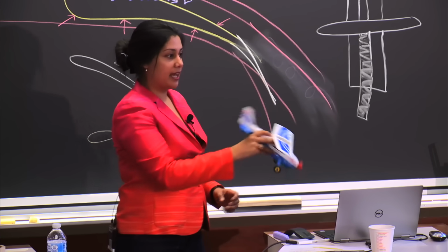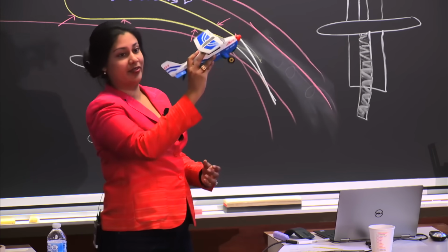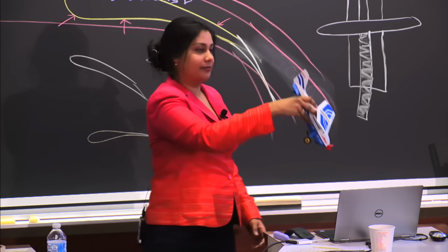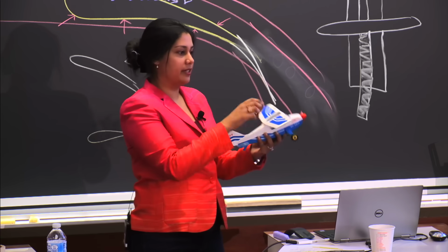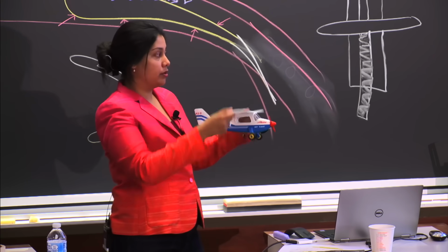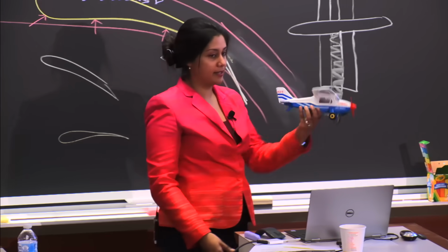So pitch nose down. You might hear that a lot in case you're getting close to stalling because your angle of attack is getting too high. They might say nose down or pitch nose down. You also have ailerons, which are out on the side of your wings, and those ailerons control the roll. So that's rolling along the longitudinal axis.